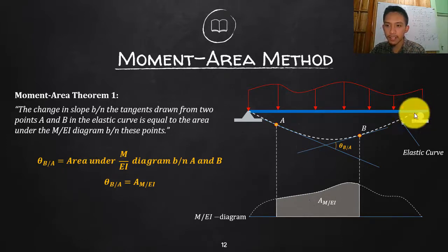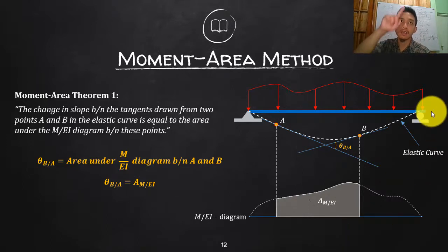If there is just a lesser load that will be handled by that cantilever, you can actually reduce the size of the cantilever beam, because the bigger the size, the beam will also carry its own weight. So if that is useless, why not make it smaller?